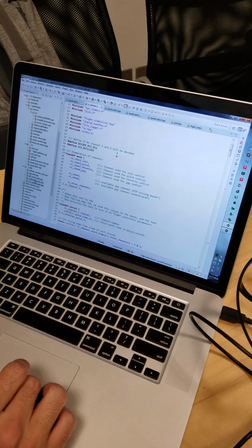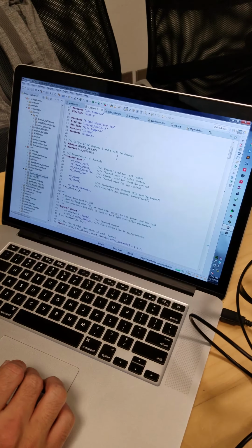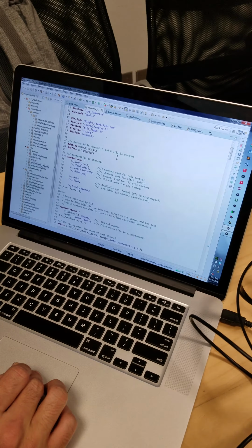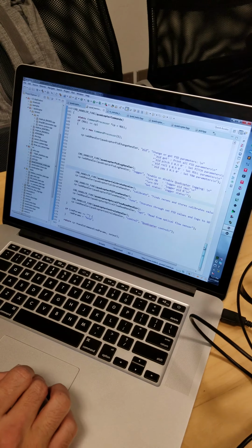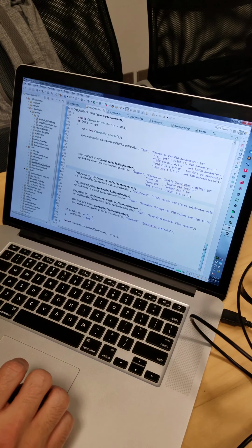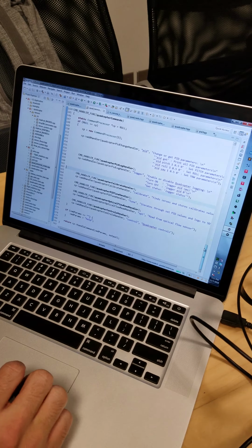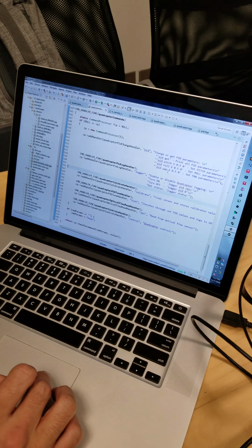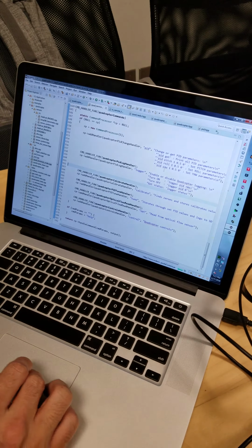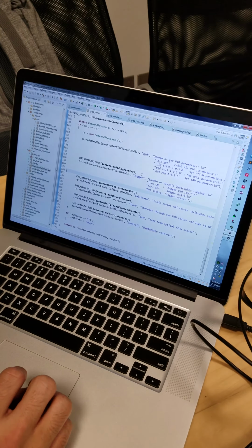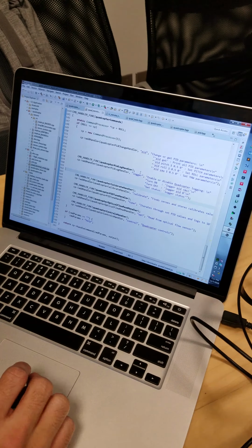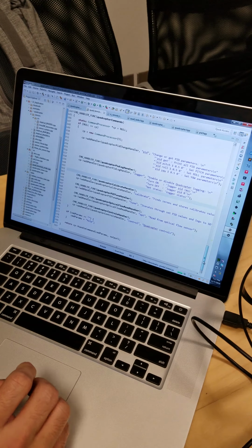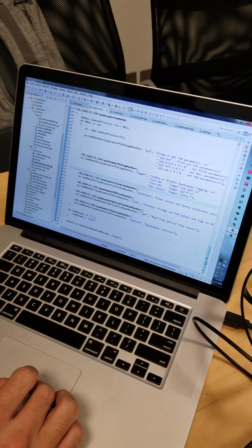And drilling down to what we use a lot of our debugging time for, we have quadcopter terminal commands. These terminal commands are accessible through a serial terminal, and it allows us to get or set the PID gains for each axis, enable logging, calibrate the sensors, or even just set some angles or controls for the quadcopter to fly.